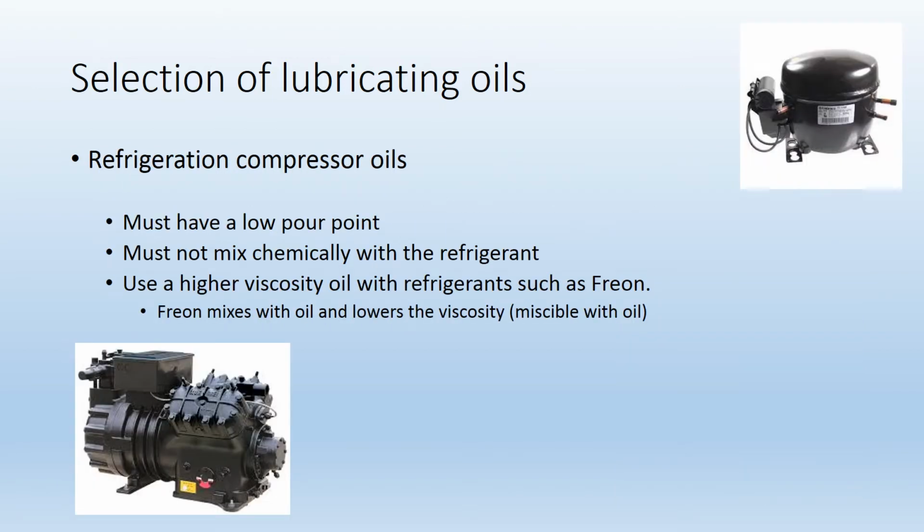Refrigeration compressor oils have to have a low pour point. They also must not chemically mix with the refrigerant. And when selecting a compressor oil, a higher viscosity has to be used because some refrigerants such as Freon will actually mix with the oil and make it less viscous. Whenever you hear the term miscible with oil, that means that the refrigerant will mix with oil.